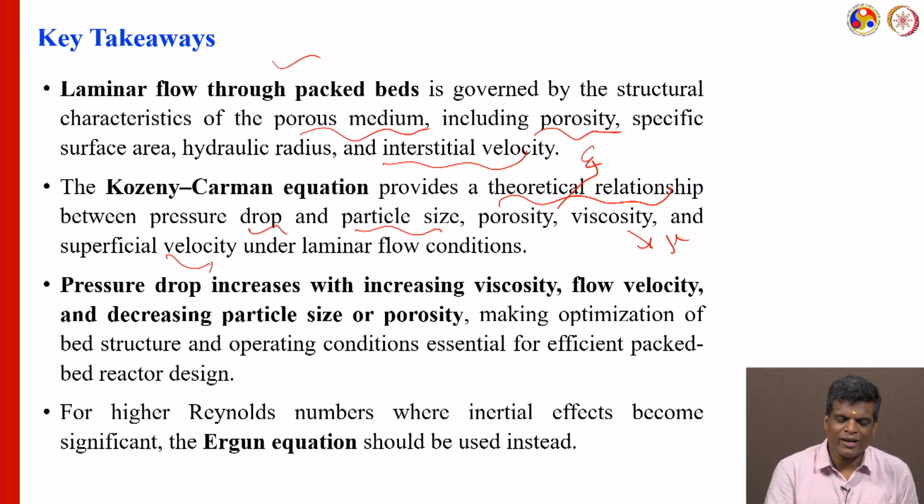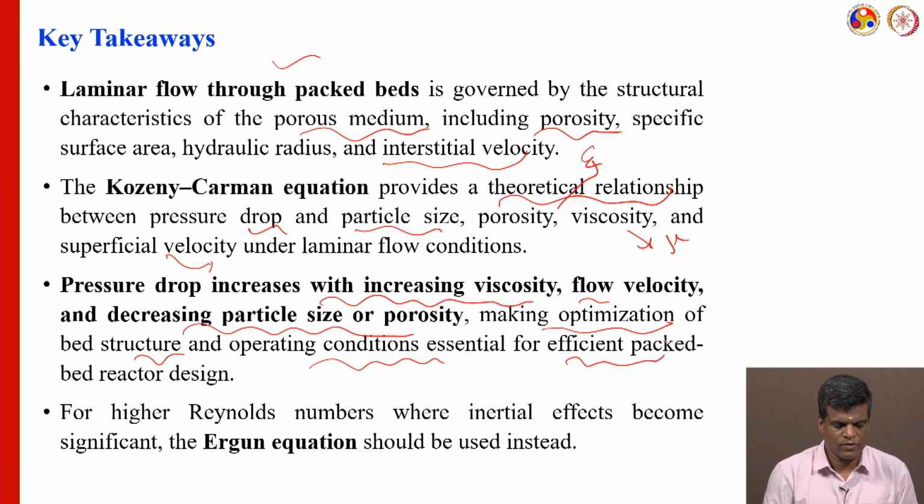The pressure drop increases with increased viscosity and flow velocity, and with a decrease in particle size or porosity. Optimization of bed structure and operating conditions is essential for efficient packed bed reactor design.